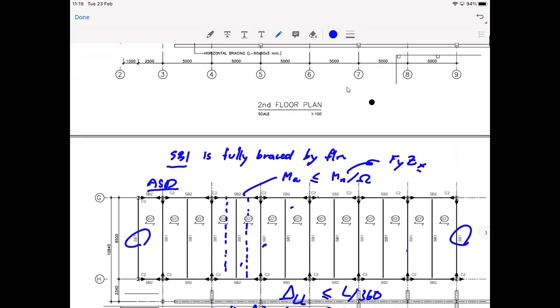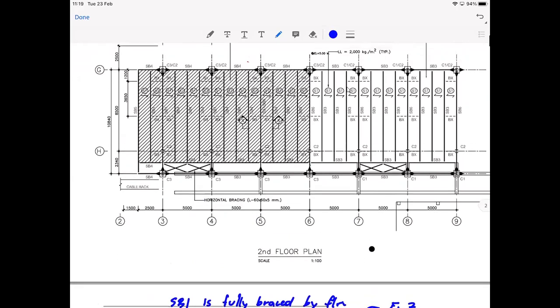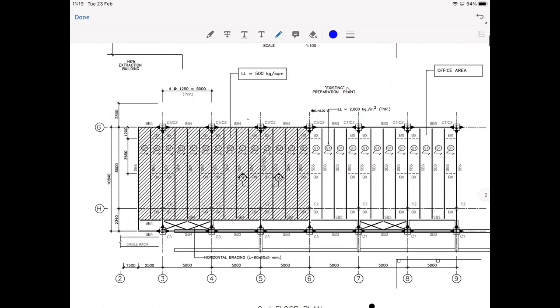Now let's go to the second floor. This time you're gonna have a lot of variations. But again, like I say, a good engineer, you should look at the load, and perhaps if you want to calculate the moment and see if you have the moment closer, if say this beam has a moment closer to that beam, so you may use the same size. Okay, you can group your beam design according to the moment that you calculate from the load before you actually start your design.